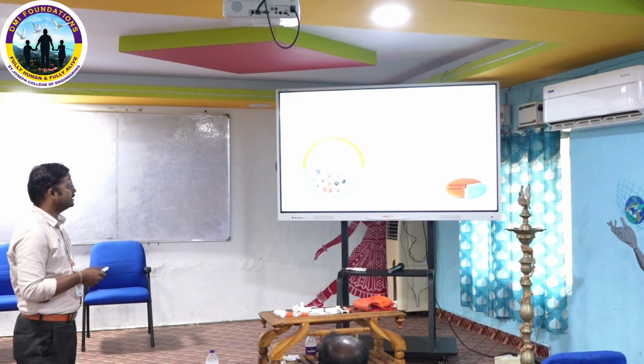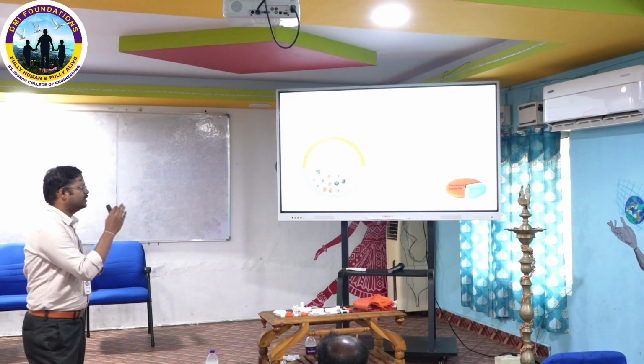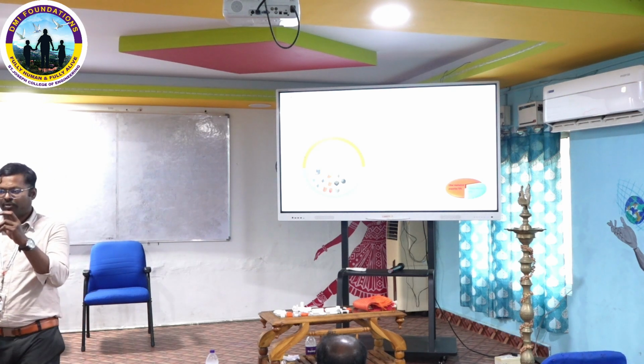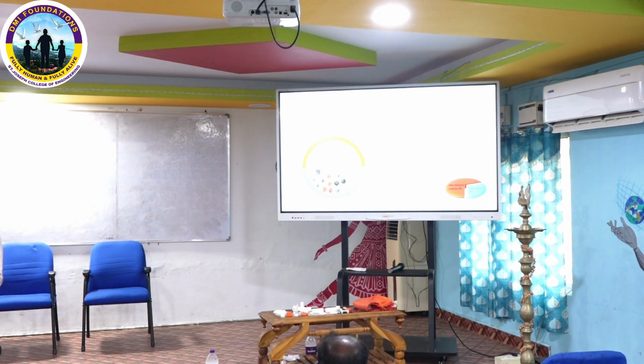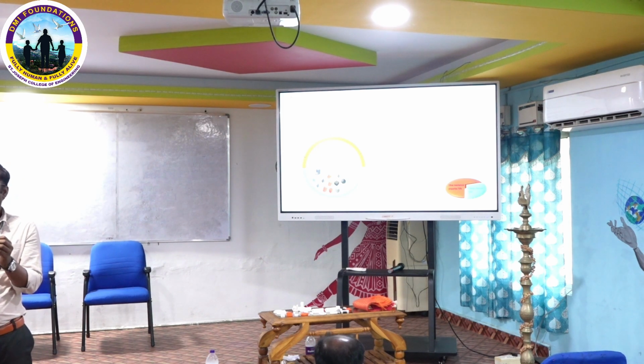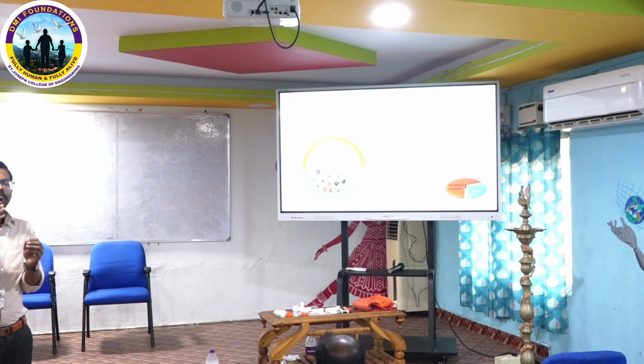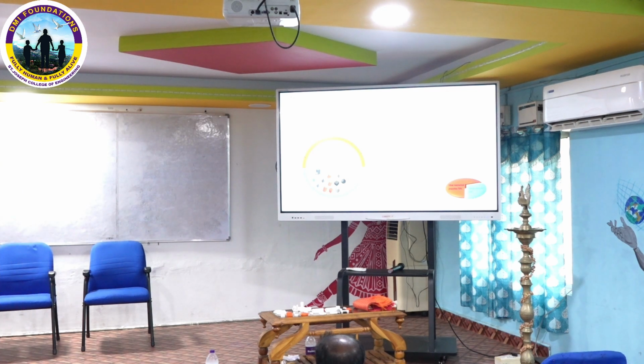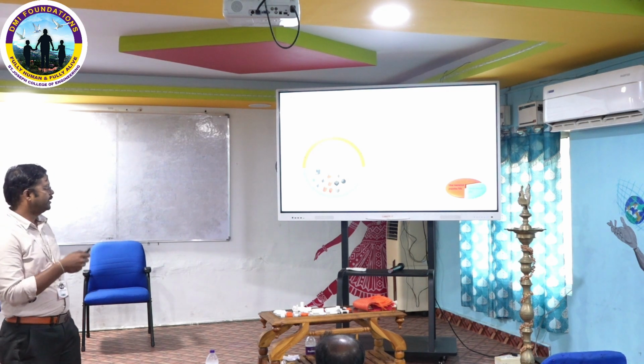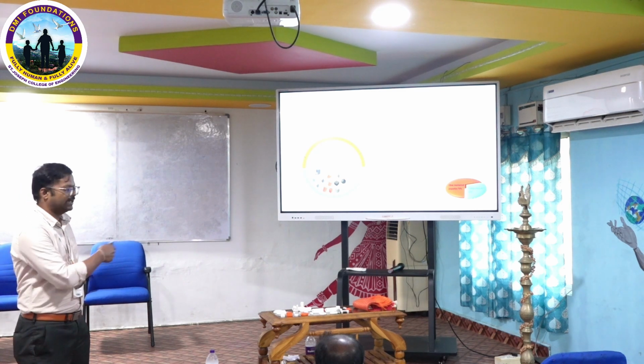Why should we go for it? It gives a high strength to weight ratio. If I have one solid cube and I load it, it will absorb more energy, but it has more weight also. Compared to that, if I go with a cubic structure with studs and more voids and load it, it will also absorb the energy, and at the same time it gives minimum weight to the component. So that is the main reason. Then it gives more thermal damping and other applications.